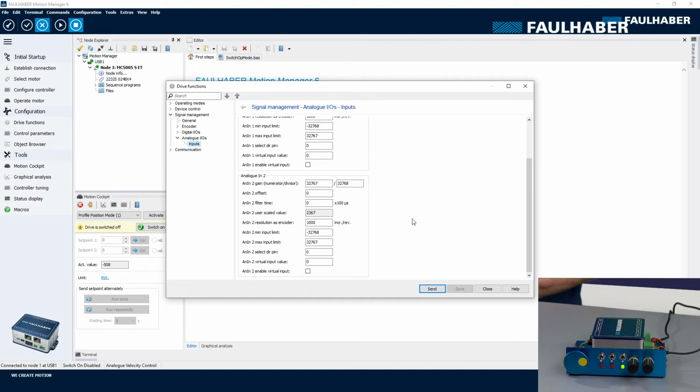It's connected to the same plus 5-volt supply, so the raw range is 0 to 5000, and I want to generate a movement of plus minus 10,000 increments out of this, and using these linear Hall signals, a single turn is 4096 increments, so that's these 2.5 turns roughly when I want to have these plus minus 10,000 increments. So to have movement in both directions, I first of all have to have an offset, and this would be at 50% of the raw range, so an offset of minus 2500, which then shifts the raw range centric around the 0. So now I got a raw input of plus minus 2500.